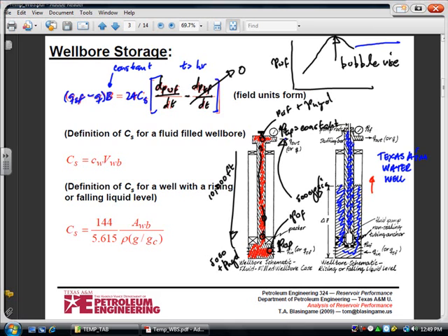What else could happen? You could burst the casing, right? Theoretically, at the bottom. If you have 5,000 psi rise to the top and then another 5,000 psi added onto that, if it exceeds the casing rating, it could burst it. I don't know of any cases like that happening. But this bubble rise thing will drive you insane because there's nothing like it.